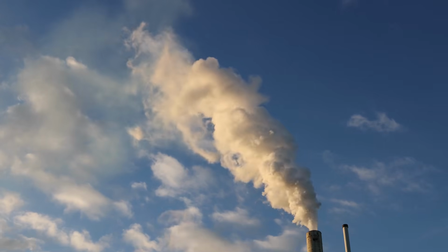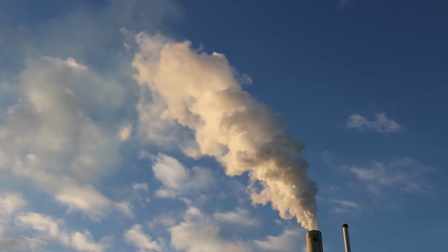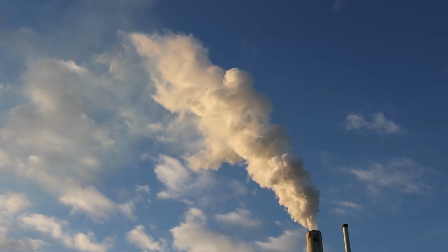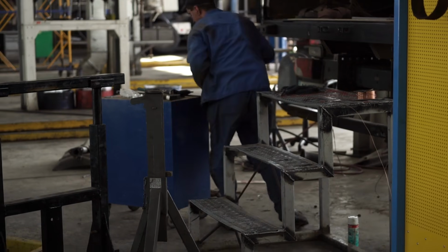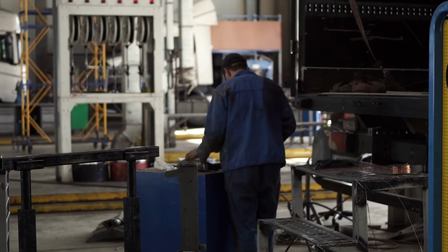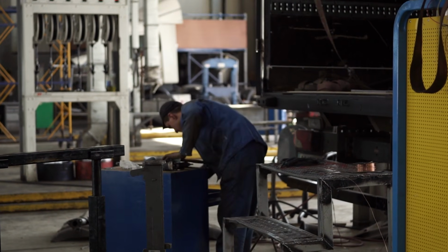G97 is the other half. Fixed RPM. You tell the spindle exactly how fast to turn, and it stays there regardless of diameter. Most operators run G96 by default. Half their jobs should be locked to G97, and the chuck manufacturer agrees with me.